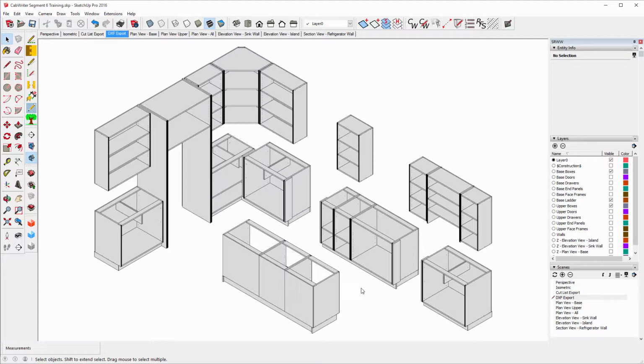Now there are hundreds, perhaps thousands of CNC machines out there, and while they all speak G code, their commands are slightly different and they're not compatible. So what we need is an application that will bridge the DXF files to the G code for a specific CNC machine. There are lots of these applications on the market. The one we like is Cut2D Pro by Vectric. You can download a free trial version from vectric.com. And that's what I'm going to use here to demonstrate this to you.